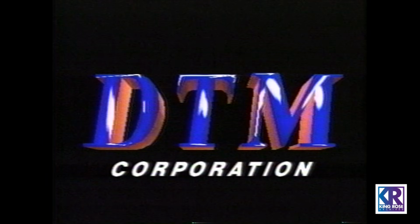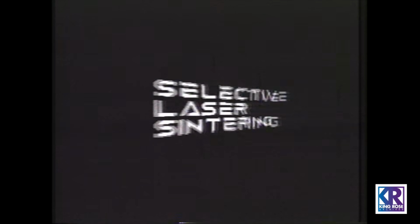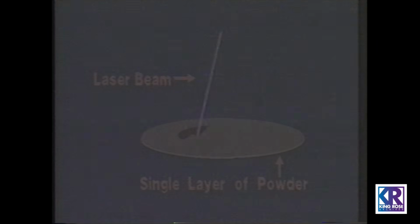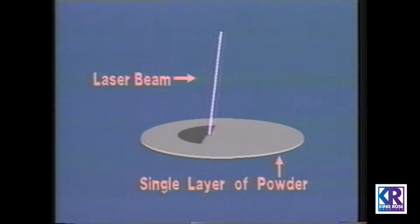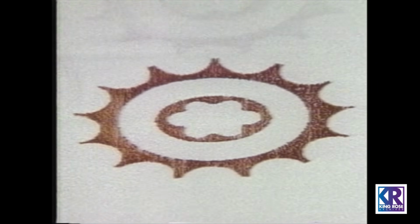Two promising methods of free-form fabrication are available for investment casting wax. The first is based on a process known as selective laser sintering. In this process, the electronic design is sliced into horizontal layers. These layers are then built up one upon another by the laser sintering process seen here. When complete, the laminations have been fused to form a solid wax model representation of the electronic design.